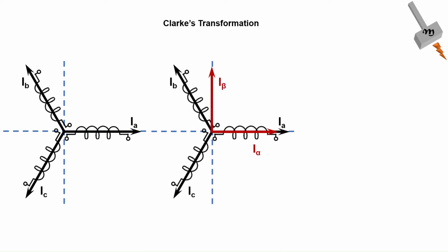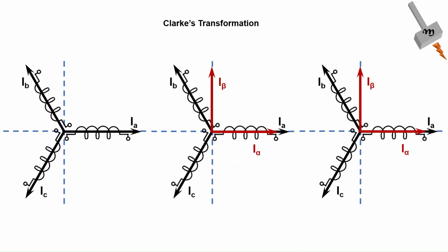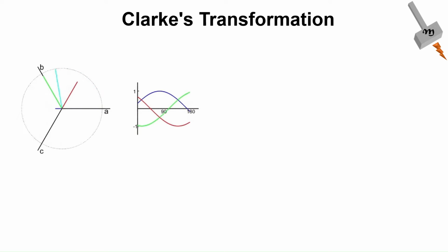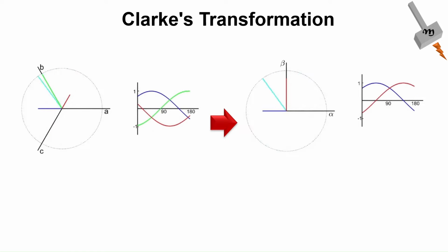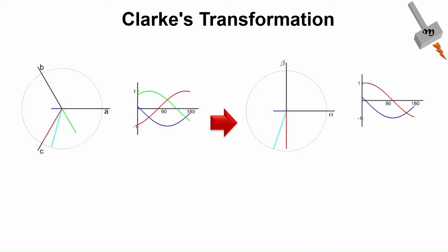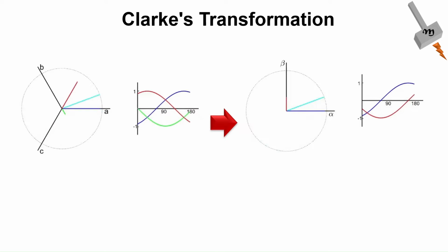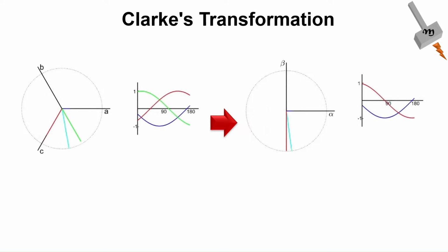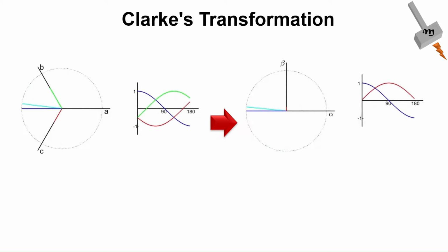The core idea is to transform stator current into a rotating reference frame using mathematical transformations like the Clarke and Park transformations. First, in the Clarke transformation, the three-phase components of the current of an induction motor are converted to two-axis vectors representing the current. These two-axis vectors are not the actual current but represent the same. The current has now been transformed into a two-component orthogonal stationary frame.